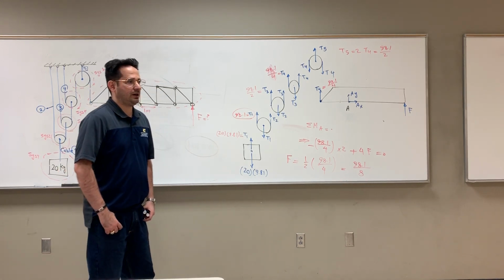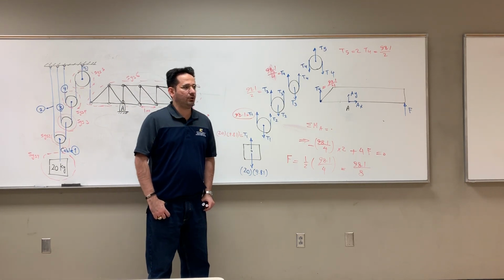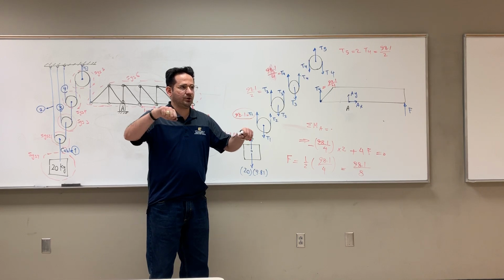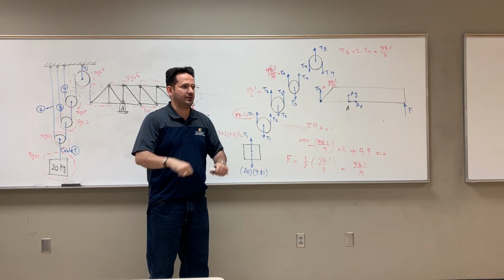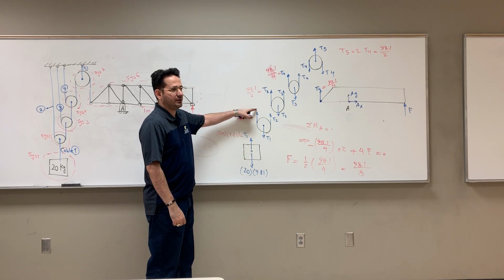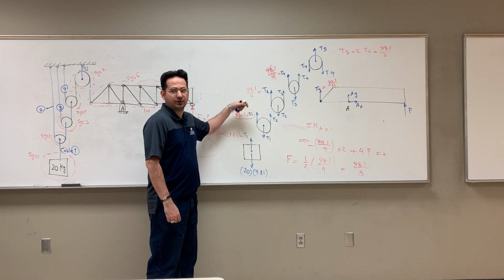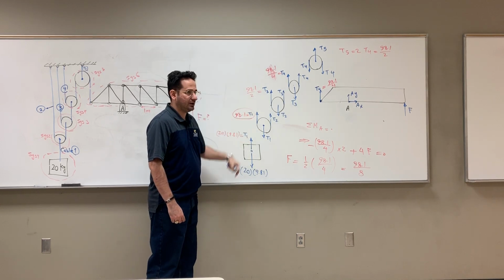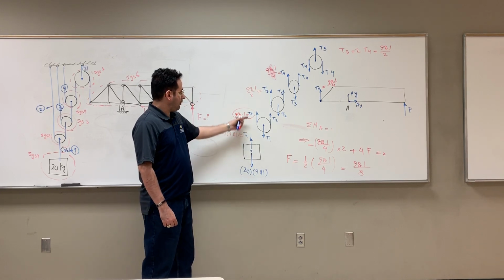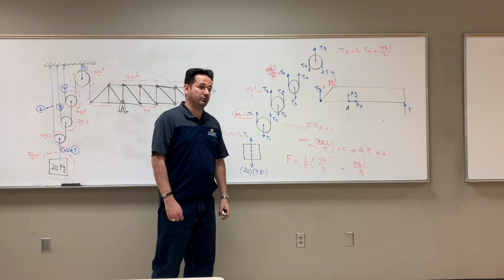Or also, you can say, well, look at the cables. What particular property do we have at cables? The tension. It should be always tension. We don't have compression at cables. So if I choose the direction this way positive, and I solve it, the final answer should be positive. Negative means compression. So all my cable forces are positive, so probably I'm doing right.